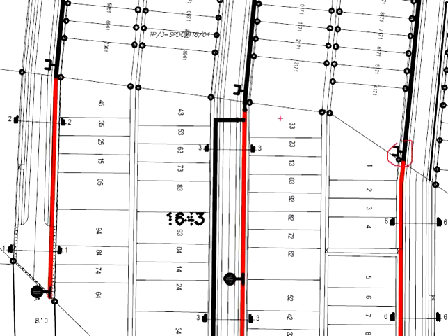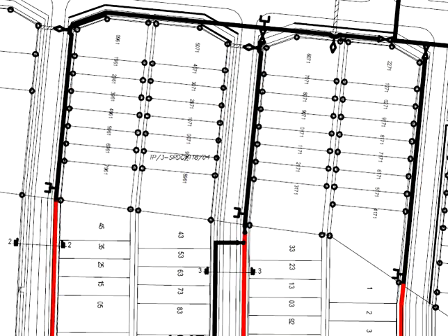At the end of each water main here, you will need a fire hydrant. Why is this so? It is because there may be sedimentation at the end of the water reticulation systems. You can take advantage of the fire hydrant here in order to flush out the sedimentation within the pipe.